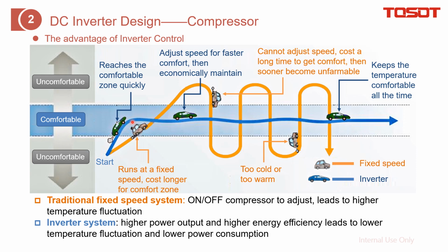After that, we can lower the compressor RPM to guarantee the temperature enters the comfortable zone. For example, if we just maintain about 30% or 40% of the max compressor RPM, that's okay to achieve your target. For this one, you can find the temperature difference is not that huge, compared with the other one.